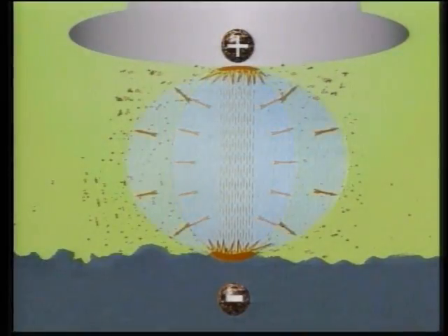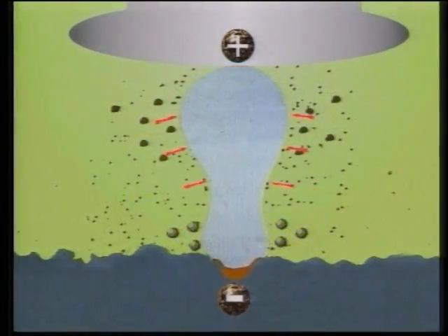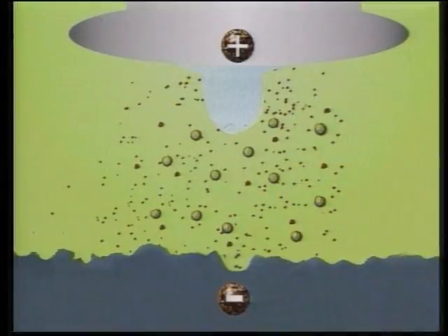A bubble, composed of gaseous byproducts of vaporization, rapidly expands outward from the spark channel. Once the pulse ends, the spark and heating action stop, collapsing the spark channel. Dielectric fluid then rushes into the gap, flushing molten material from both surfaces. This EDM residue consists of small solidified balls of material and gas bubbles.